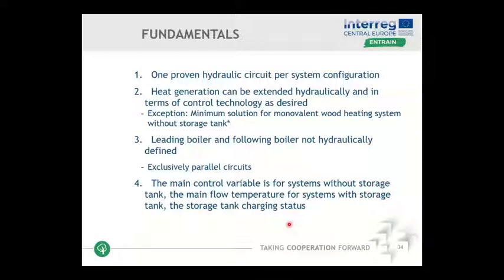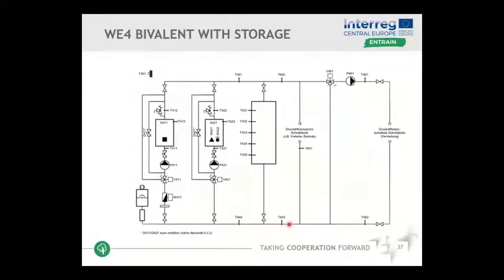Okay, so now I jump into an even more complex topic. This is the hydraulic schemes. We're talking about something like this. This is an integral part of this dimensioning process of choosing the setup, and I try to provide some fundamentals for this process. As I said, and I want to highlight it again here, this is not only a hydraulic scheme. It's not only about the piping. It's not only how we connect these boilers. It's an integral process. We have a hydraulic scheme for each boiler plant setup, but this is connected to a control strategy. This is connected to a measurement standard, at which point we measure what, to a monitoring concept. So it's an integral concept.